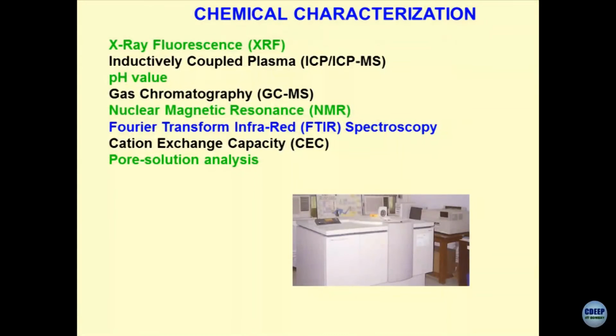of these gadgets. One of the tests which is done to establish the chemical characterization or the potential of the geomaterials, whether they are chemically active or not, would be cation exchange capacity, CEC. I will be talking about this. It is a simple test, and it tells you quite accurately what is the potential of a geomaterial to interact with the environment, how reactive it would be, how active it would be.